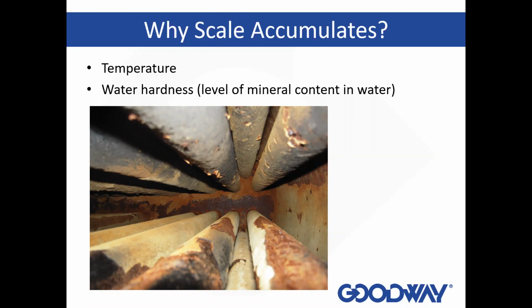I've seen boilers where there's so much scale that the tubes actually come, there's a term called bridged, where it looks like you literally have backed up a cement truck and poured cement in. You can't even see the differences in the tubes. It's really counterproductive to run a boiler like that, because there's no heat transfer anymore. You can actually even melt the boiler tubes because the water steam mixture on the water jacket side is actually acting as a coolant, paradoxically.